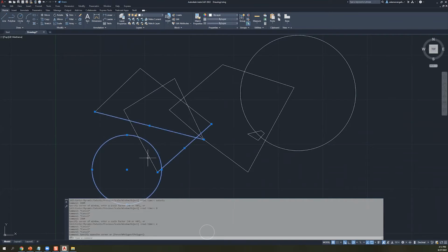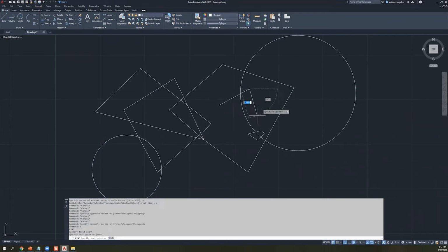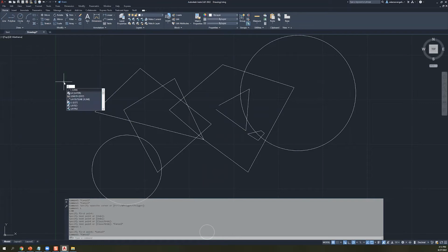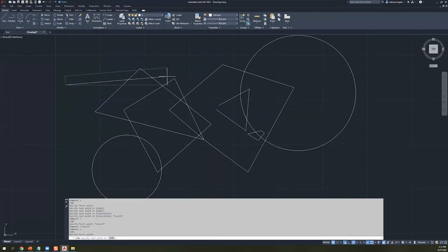So AutoCAD does a lot to auto complete your statements and try to understand what you're trying to do. And a lot of it's pretty intuitive, surprisingly so, I would say. Like line, what do you think the command is for line? Okay, well, you just need L, and you can just press enter, and then you could start going through there, right? Now, similarly, you could use space as an entry button as well. So if I just have both my hands on my keyboard, I type in L, I press space, and I'm initiating the command itself already over there as well.